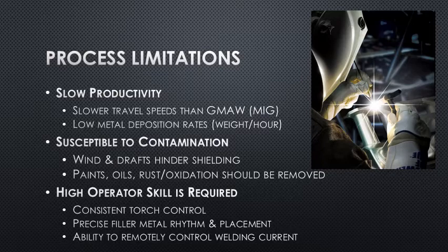And the ability to remotely control welding gives the operator the ability to adjust the arc based on puddle width, which usually determines how much current they're putting in. A wider puddle usually means we're using more heat, and a narrow puddle means we're using less heat. So the operator can make that judgment call and make judgments on the fly.